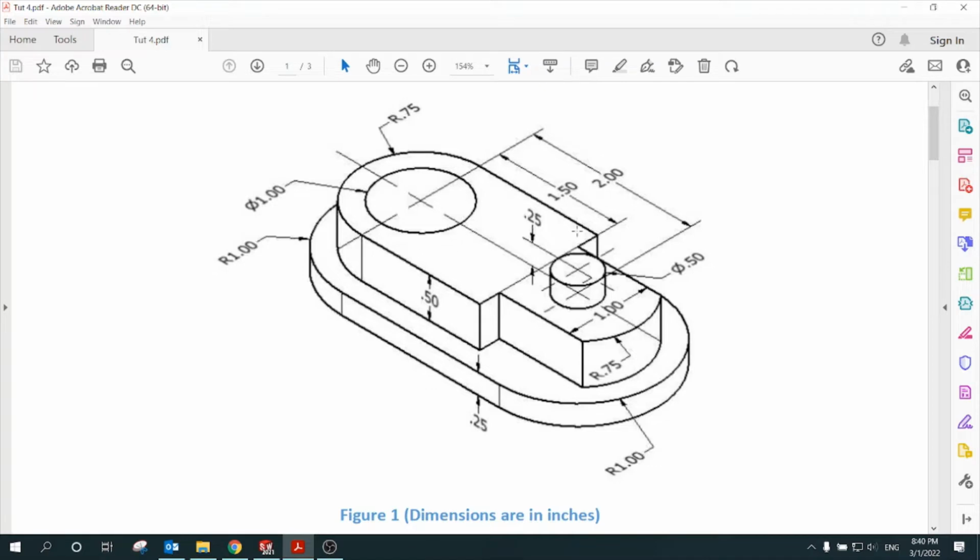with 2 lines, and then we go to inside, one line, half circle almost, and then line and line. This is the second segment. It has a thickness of 0.5. And finally, we will make the small cylinder with a diameter of 0.5 and height 0.25. Now, the 3 features are made on the top view.